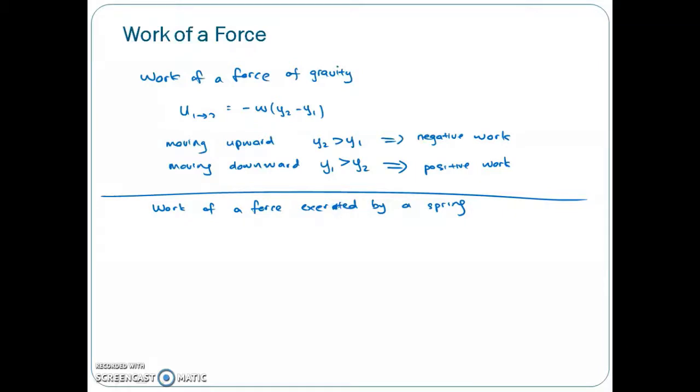When the spring is undergoing extension, the work of the force of this spring from position 1 to position 2 will be 1/2 k (x1 squared minus x2 squared).